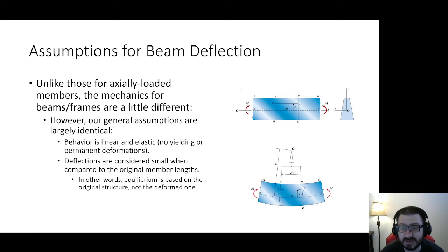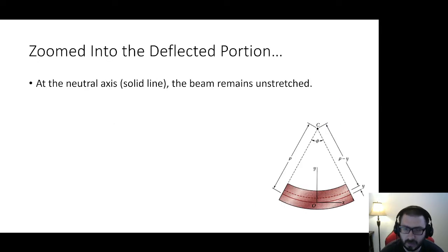There are some instances where engineers do have to handle that. It's what's called a second order analysis. You'll find that a lot in tall building design under wind and earthquake, where you have to consider second order effects. We're not really going to worry about that for this, and that's sort of an advanced structural analysis topic as well. When we're just getting into it, we're going to keep things simple.